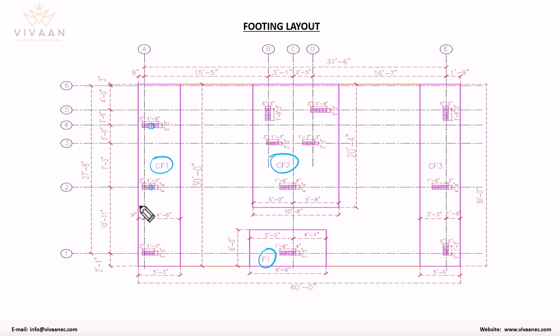So basically one thing which every client needs to remember is that when we give the drawings, we'll be giving you the recommendations. So besides these drawings, what do we need to follow, right? We will be giving you the grade of steel you need to use, and the grade of concrete you need to use. And even in the grade of steel, we will be specifically mentioning it as 500D or 550D.